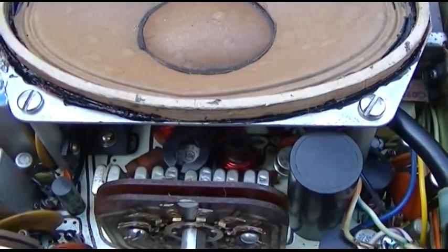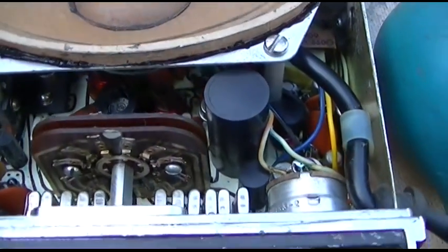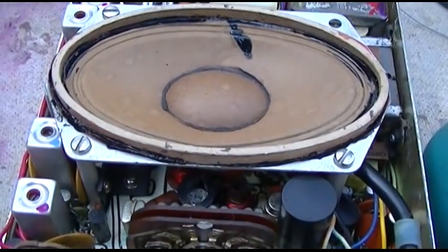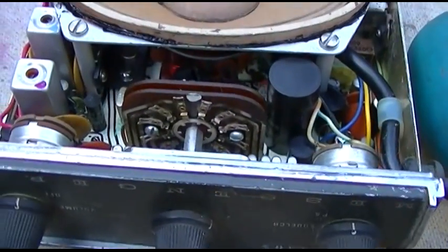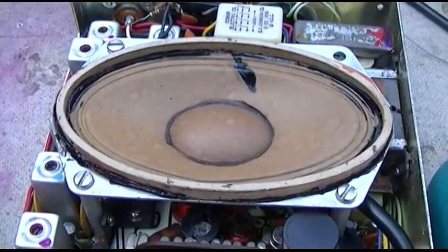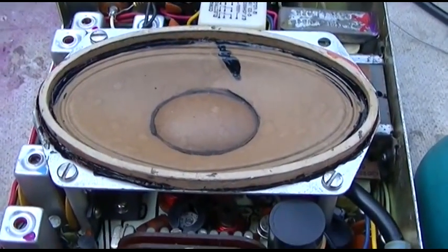Well, you can hear the difference with no antenna connected just by replacing that capacitor, and since that capacitor was in the audio circuit, it should increase the mic gain and modulation that much too.